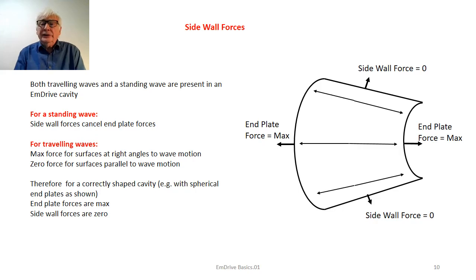There is a common misconception that in a tapered cavity, the difference between the end plate forces will be balanced out by the forces created at the side walls, the tapered side walls. Now, if there was just a standing wave in the cavity, this would be true. But the standing wave is due to a travelling wave going backwards and forwards along the axis of the cavity.